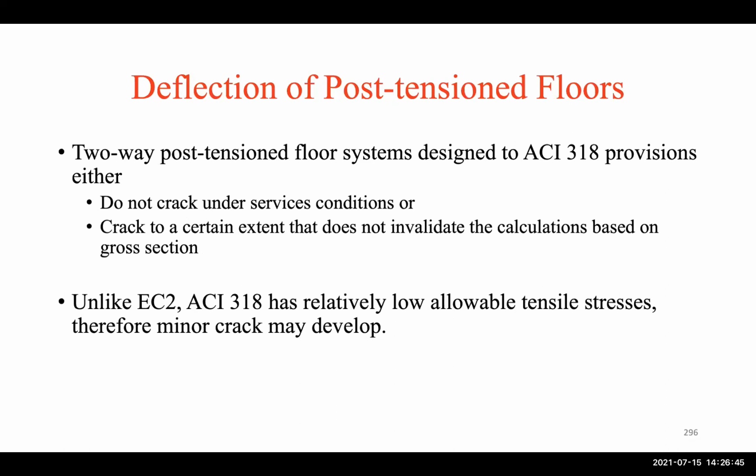Okay, now for post tension floor systems, they either do not crack under service conditions, that's uncracked, or crack to a certain extent, but that does not invalidate the calculations based on the gross section. So there's some cracking, but we can still use the gross cross section. So that's important here.